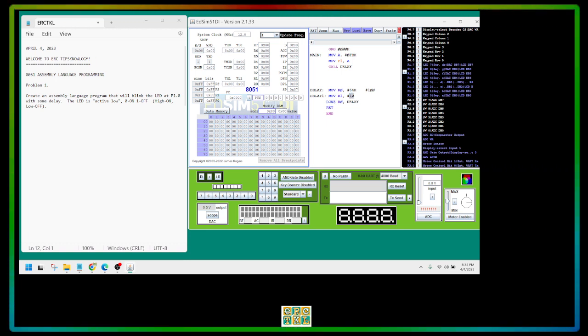But if you want to write it in hexa, then it will be 0A hexa. So what will happen here is that register 0 will be 64H, register 1 will be 0AH, and then we will decrement the value of R1. So we will put DJNZ R1, and then we will tell where it will go back. So let's say it will go back to again.